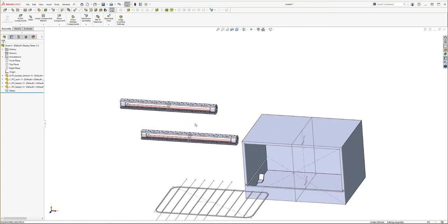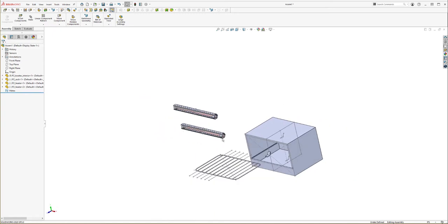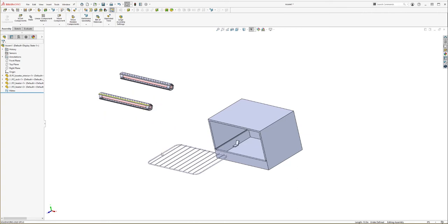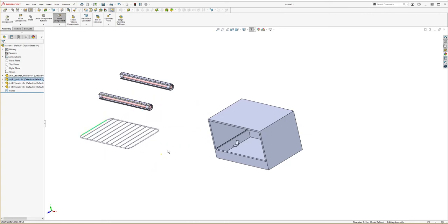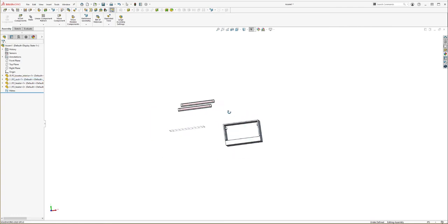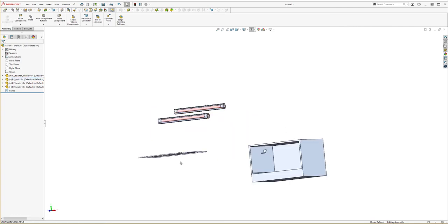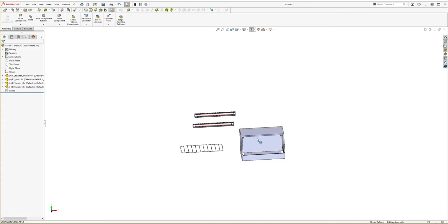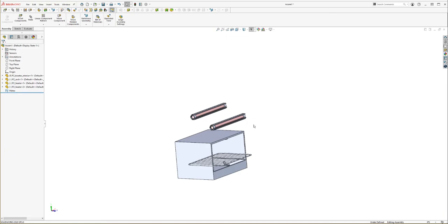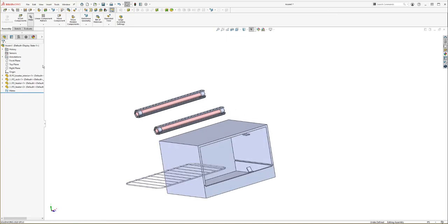You can see the different ways that I added files into this assembly was by clicking the green check for this first one, where it's fully defined and aligned with the planes, and by clicking in the viewing window for these most recent three. You can see that these are not fully defined and actually float around and can be placed wherever I want. Now, we want to align these to the main interior, and we're going to do that with a command called mates. It looks like a paperclip here. So I'm going to go ahead and load that command.